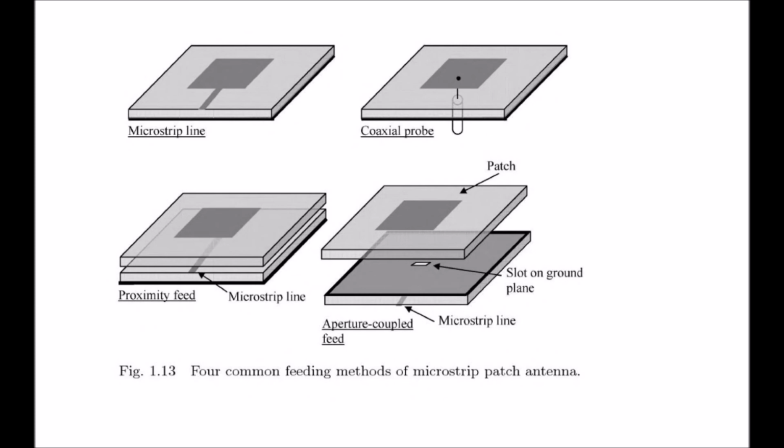Number 3, while a single patch element generally incurs very little loss because it is only about 1/2 wavelength long, microstrip arrays generally have larger ohmic loss than arrays of other types of antennas of equivalent aperture size. The ohmic loss mostly occurs in the dielectric substrate and the metal conductor of the microstrip line feed network and power dividing circuit.